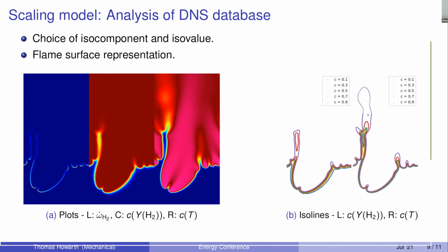We have this flame surface that balloons into the post flame, as we call it. So instead, we define our surface based on a value of fuel mass fraction, say a fuel mass fraction of 0.1 or something, and we found that this aligns far more closely with the fuel consumption rate. This allowed us to take statistics from the flame more accurately.